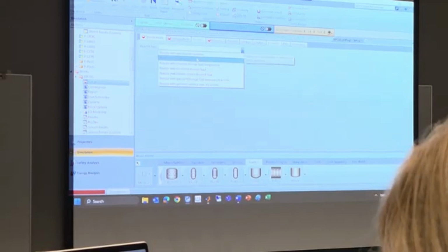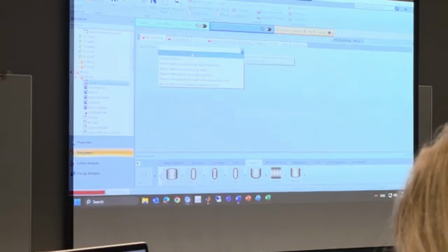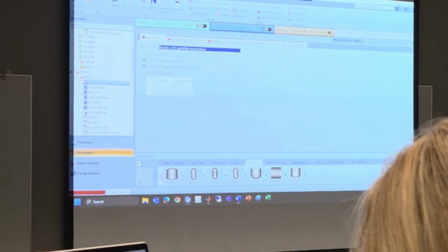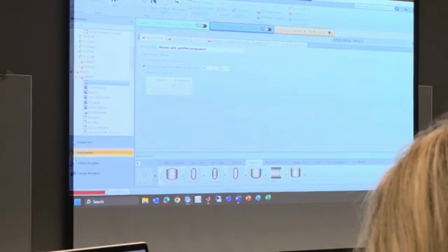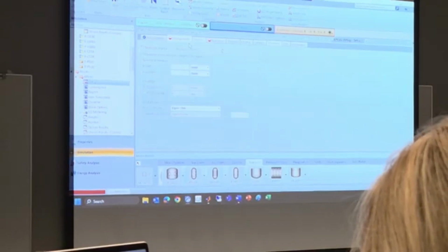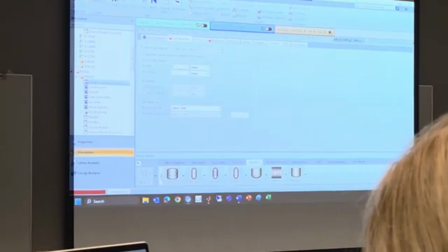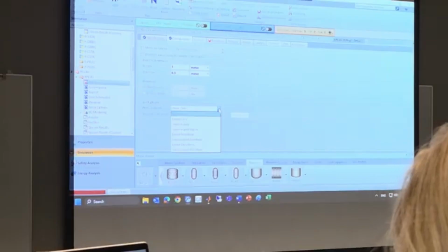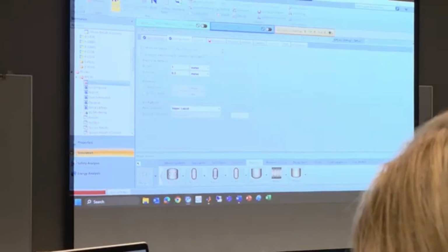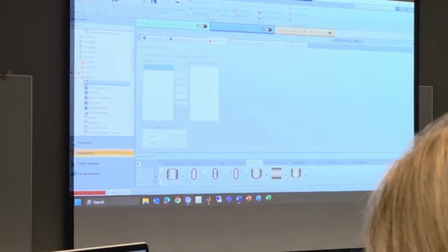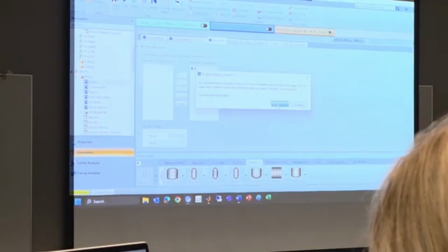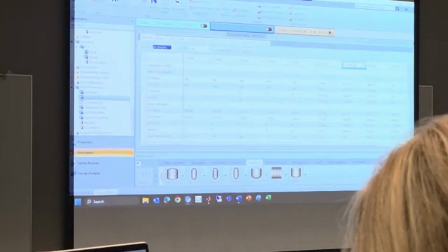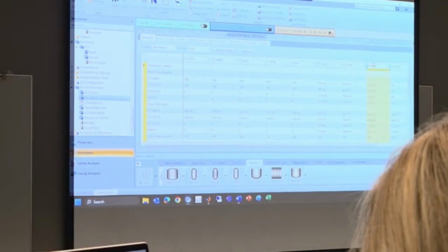We have specified the temperature, so you can choose from the drop-down arrow. We have temperature, so I use that information, which is 70 degrees Celsius. Then configuration, length: you just put any number here for simulation purposes. Phase, vapor-liquid. Reaction: we already defined R-1, so I can use the same one. And you can check the result from the plug flow reactor product.